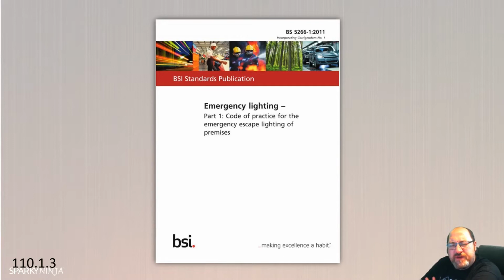When it comes to BS 5266, there's more information, with regards to duration, due to time, due to lux levels, due to space, due to passing width restrictions. So there's a lot more into it that you need to, if you're involved in emergency lighting systems and you're doing a design of emergency lighting systems, the range of BS 5266 is very important. And so they supplement BS 7671.